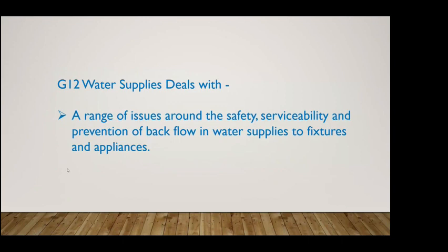G12 is all about the water supplies, so supplying water at adequate temperature. So if it's a personal hygiene fixture, it will have to be tempered to 45 degrees currently. It's likely that they're going to change that to 40 degrees. That's what they were consulting on recently. So eventually,